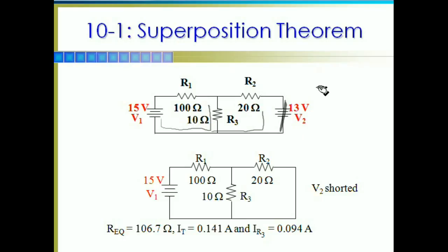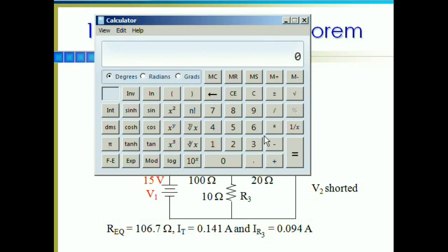If we look at the equivalent resistance of that parallel circuit, I'm going to need my calculator back up here. I've got 10 ohms plus 20 ohms, and of course I'm going 1 over x because I'm taking the conductance of the two, adding the conductance, taking 1 over, and our equivalent resistance is 6.67.